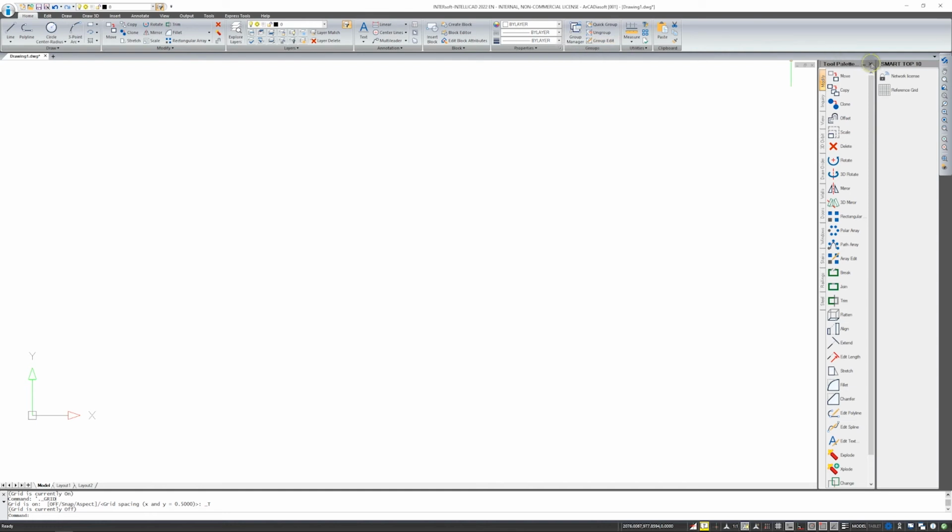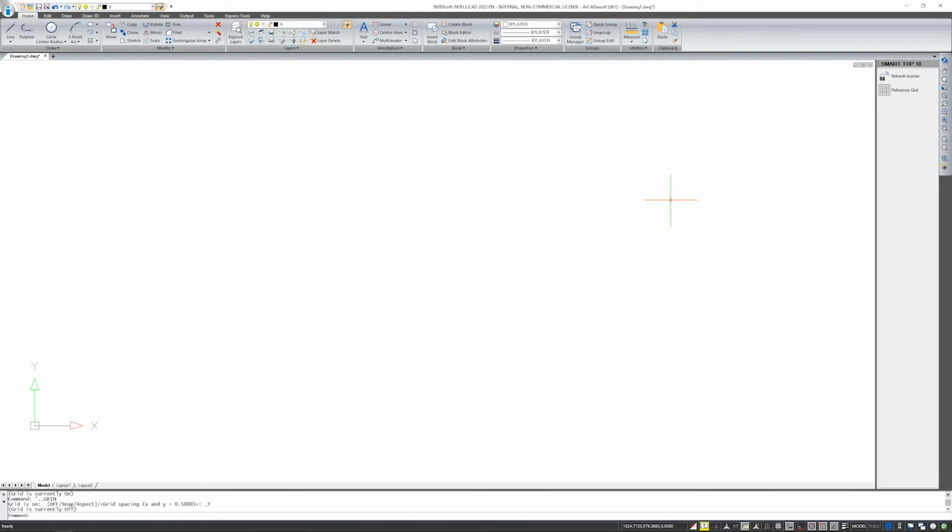I will close my palette and I will add elements that may be useful in a moment. Let me start by saying that I should divide the drawing into layers. You can do it at any time. You can do it before you start drawing. You can do it after. I'll start drawing without layers. I'll be drawing on layer 0. Switching between layers is on both the quick launch bar and the start ribbon, depending on what you have at your disposal.